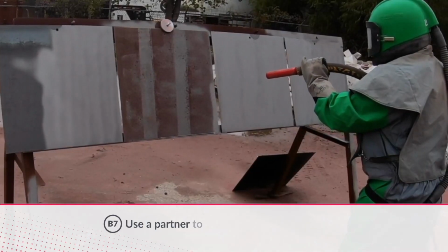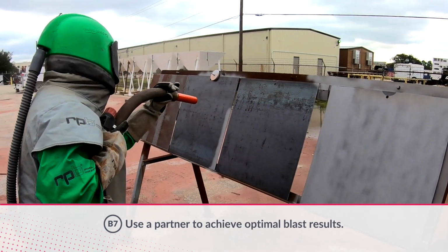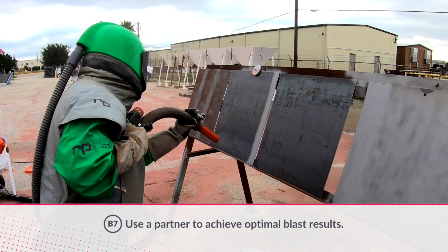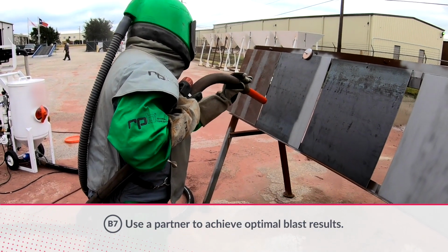Have a separate person adjusting the metering valve in line with the blaster's instructions. While blasting the surface, move the nozzle to determine whether your cleaning rate is acceptable. When using GMA Garnet, the abrasive exiting the nozzle should be almost invisible if the blast equipment is correctly set up.